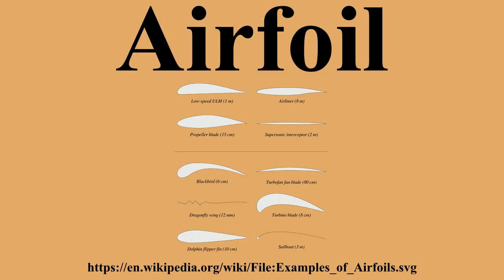Supersonic airfoils are much more angular in shape and can have a very sharp leading edge, which is very sensitive to angle of attack. A supercritical airfoil has its maximum thickness close to the leading edge to have a lot of length to slowly shock the supersonic flow back to subsonic speeds. Generally, such transonic airfoils and also the supersonic airfoils have a low camber to reduce drag divergence.